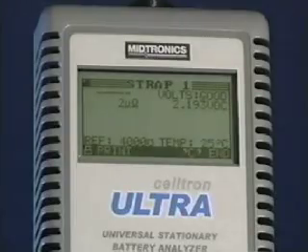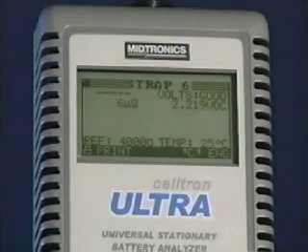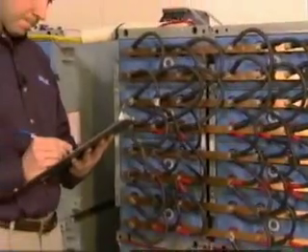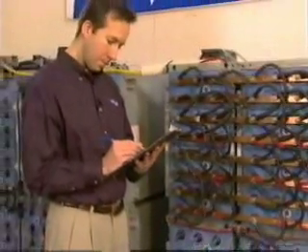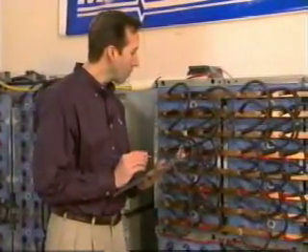You can scroll through all your collected information to locate a pattern. The resistance or voltage drop in each of these battery measurements and strap measurements should be fairly even. Anything unusual indicates a potential problem with the strap. That completes basic testing information for string 1 at this particular site.